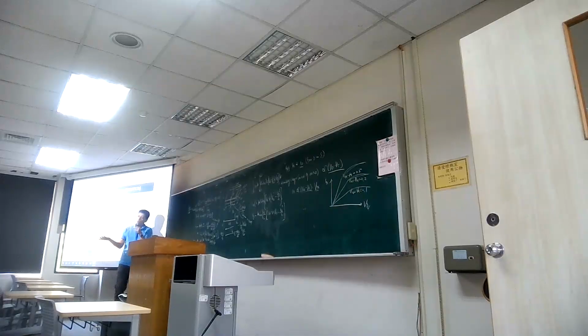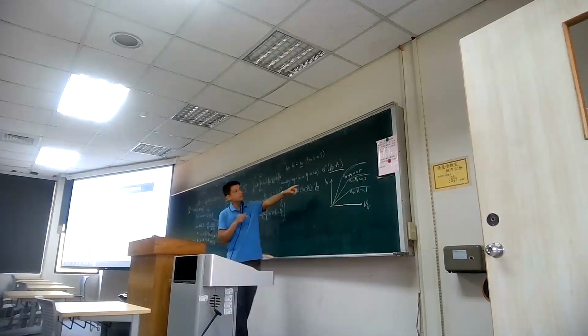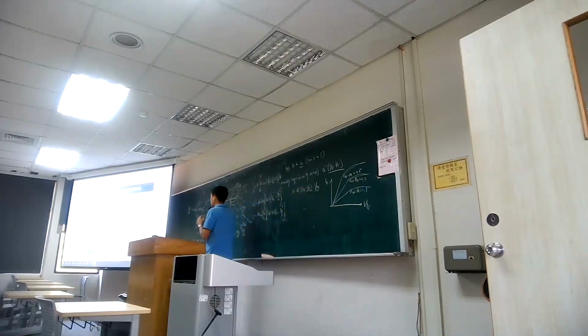Okay, so that's simple. Why do we divide by L? If you get a shorter channel length, of course you get more current. Okay, and that is multiplied with VGS minus VT, depending on how much accumulation charge along the channel. Multiplied with VDS, just like the terms we have here. Okay, but there will be an additional minus 1 over 2 VDS squared.